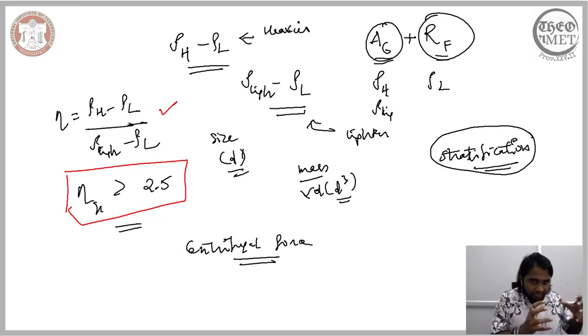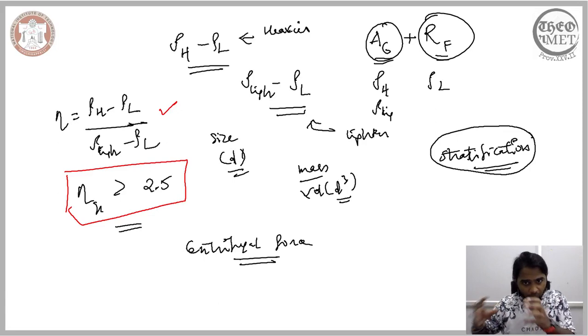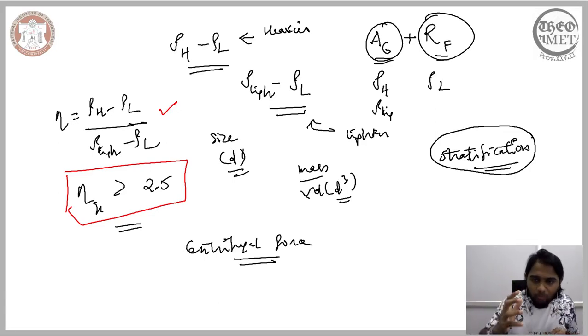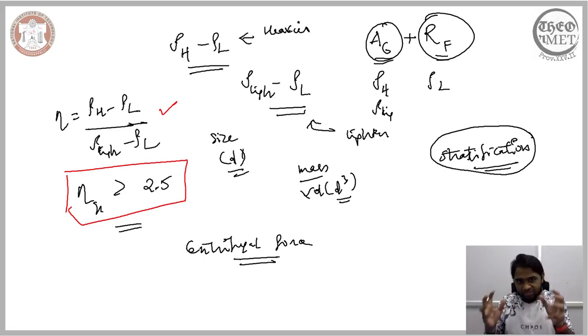So again, after quantifying the efficiency, now to further improve the efficiency, particularly when you have a mixture with a large fraction of the smaller particles, you augment your gravitational force with centrifugal force in order to ensure that you are able to achieve a sufficient amount of separation, and its efficiency is ultimately higher.